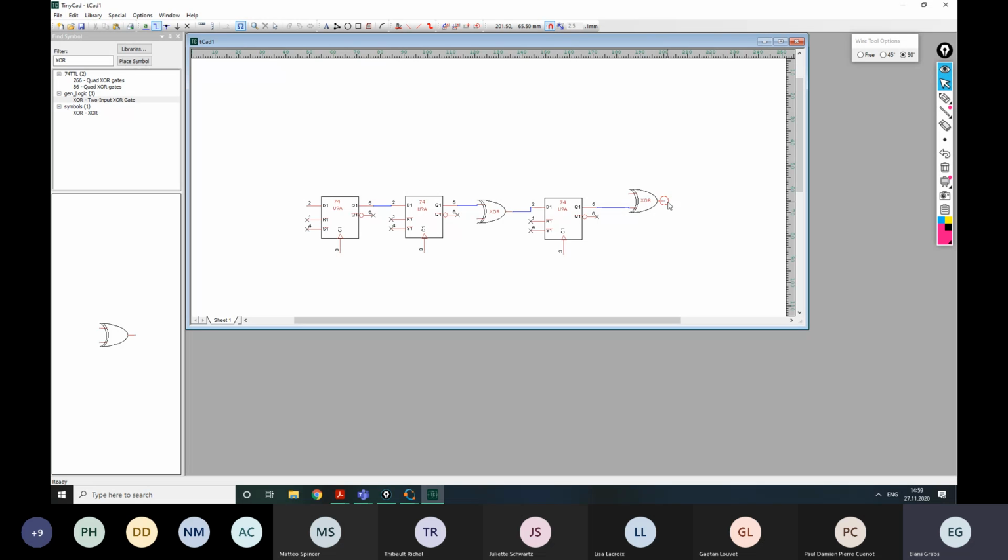And now we need the feedback. The feedback is connected to the input of the first flip-flop and to this XOR element second output, right? So this is the schematic for dividing data block with generator polynomial.